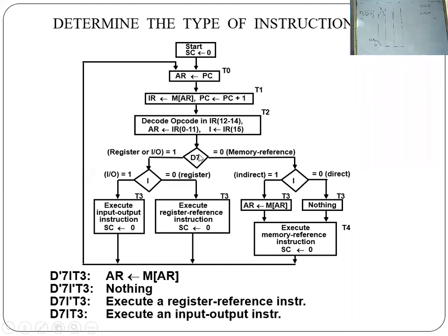So now, which bit will help you decide whether you are going to perform the memory reference operation or the register reference operation? Let me make this point clear. If you remember your instruction formats, we have covered three instruction formats. First is memory reference, the second is register reference, and the third one is IO, input/output reference instruction, right?